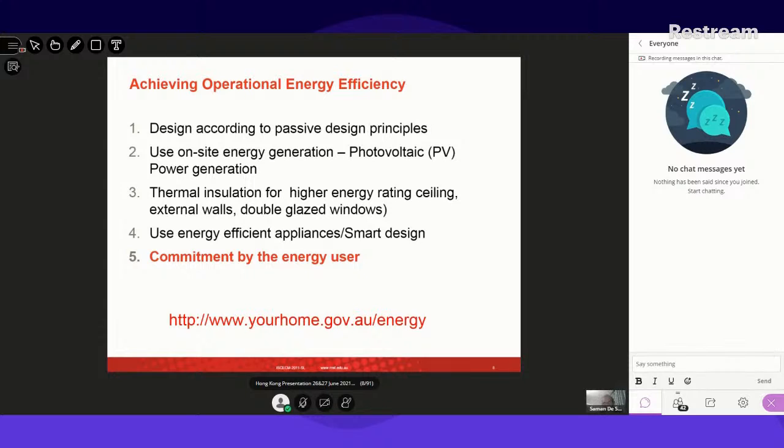If you draw a simple rectangle with two outlets, one at the bottom and one at the top, with the colder side at the bottom and the warmer side at the top opening, it will create an internal draft, which will keep the interior thermal comfort pretty good.